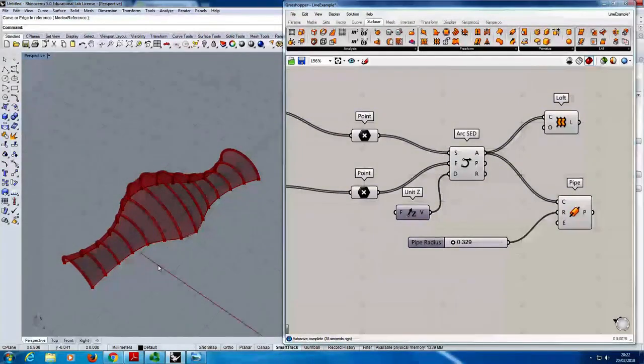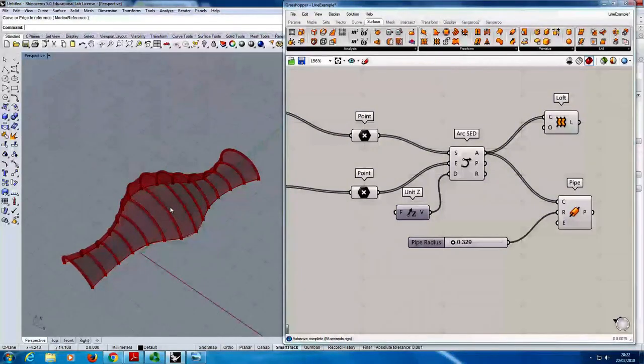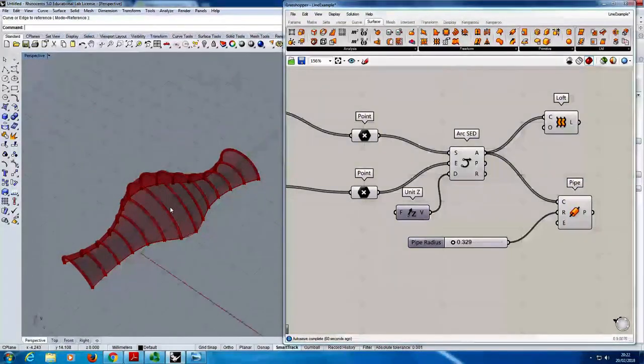And therefore, some of these arcs, or some of these arches are going to be working harder than others because they're going to be spanning further, supporting more weight. What I might want to do is therefore not have the same cross-section for each one of these ribs. Some of these I might want to have a deeper section. And maybe what I want to do is to have Grasshopper automatically select the size of that section for me based on the geometry. So now I'm starting to input my design thinking, my structural knowledge, and I'm starting to embed that into the definition.